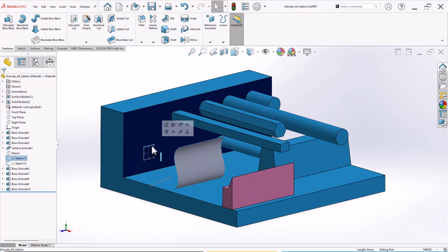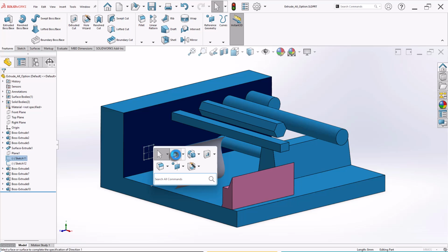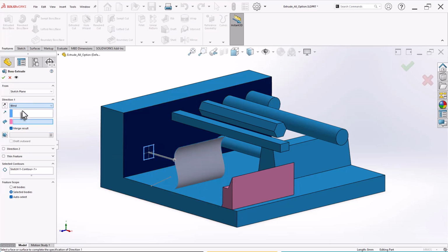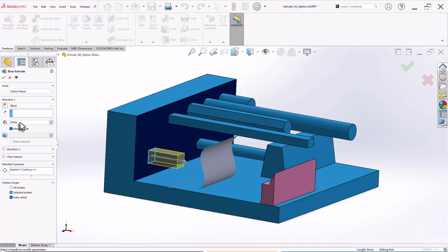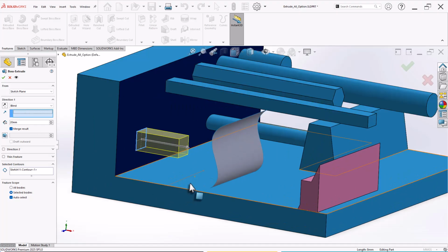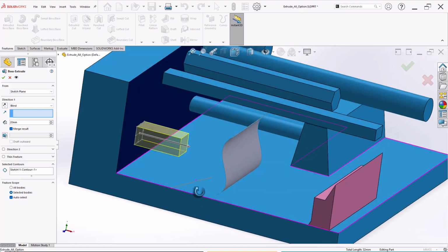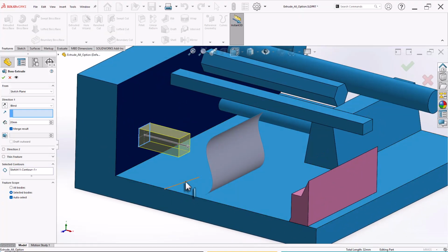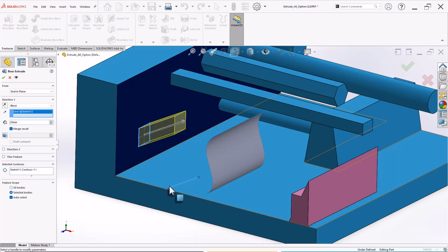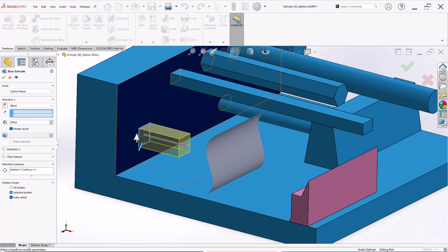Let's try another option. Here, choose this sketch and press S key and select the extrude. This time I will go for blind. Here I will keep the 20 millimeter, but there is one option called directions. Select this part, and this small line, which if not visible, try to move your model by pressing the middle mouse button and choose this line. In this direction extrusion will happen. If you untick, let's say clear it, it will happen perpendicular to the sketch plane.